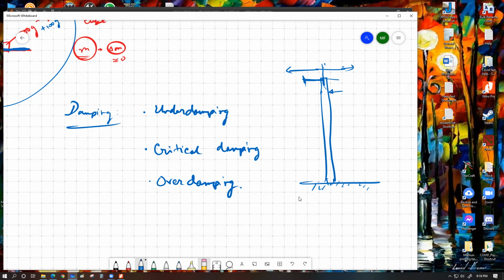As you slowly go higher above, the speed of wind becomes significantly high. The kinetic energy of the wind is really strong at a higher level of atmosphere. So if you have a really tall building, you're going to have different values of air pressure at different parts. So it is possible that a tall building might actually undergo resonance for a certain type of wind pressure or for a certain frequency of the earthquake, and that might lead to severe damage and loss of lives and whatnot. So we install this kind of critical damping mechanism.